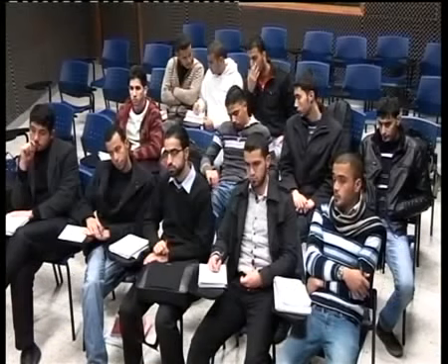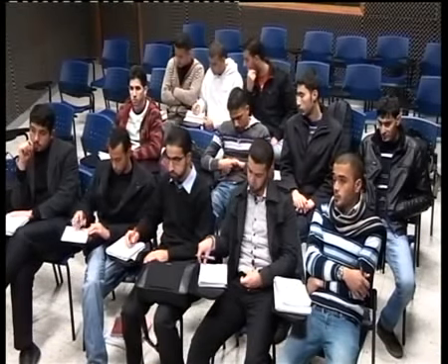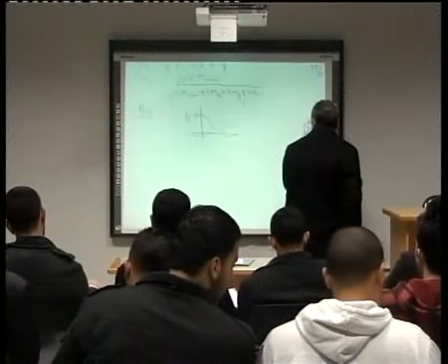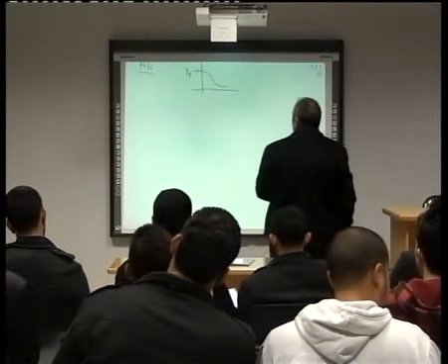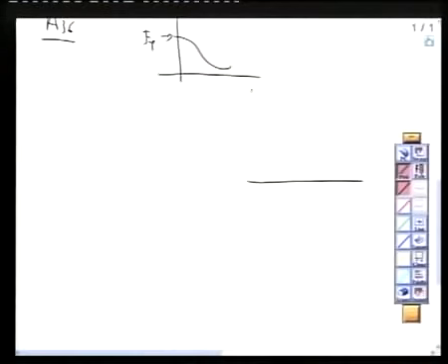Beam columns, you are combining beams with what? With columns. And let me remind you that we have many interaction curves. And we decided to put an interaction curve which represents a lower bound, and it came something like this.